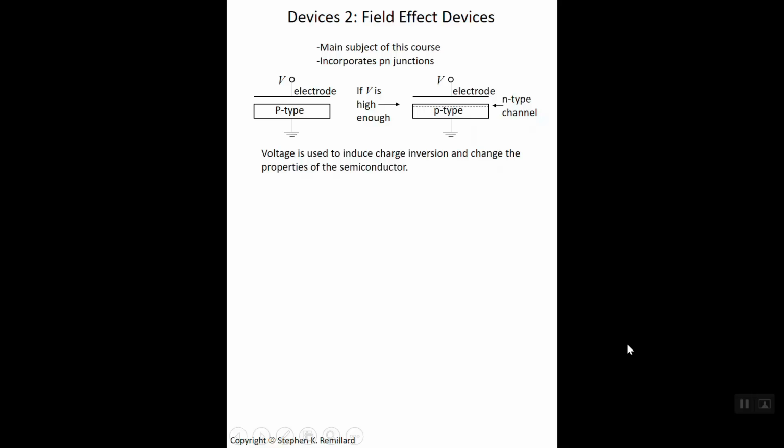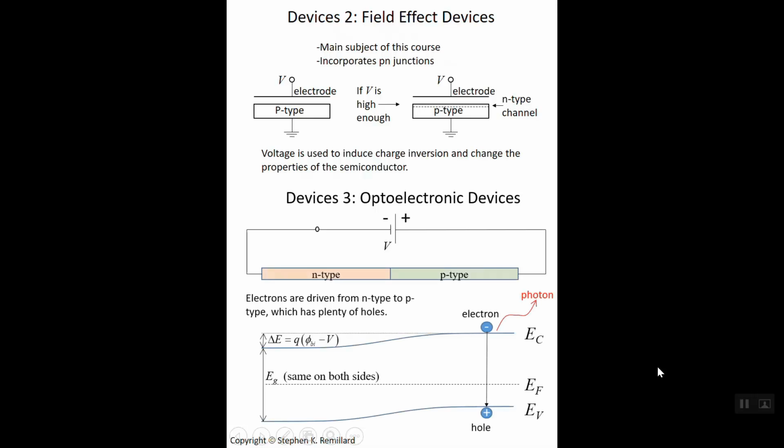When we finish PN junctions, we will do an entire unit on optoelectronics, LEDs and LED lasers. Light-emitting diodes are based on a PN junction. When you forward bias a PN junction by putting the positive external voltage on the P side and the negative external potential on the N side, the bands become less bent. The conduction band edge moves up in the n-type, and there's less of a potential hill for electrons to climb to get over to the p side, so they do. And they go over to the p side.